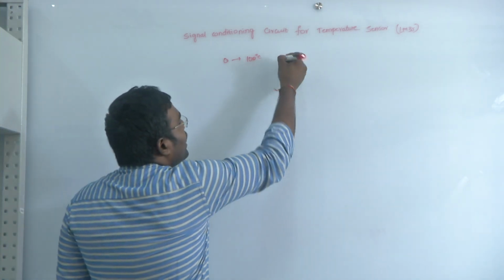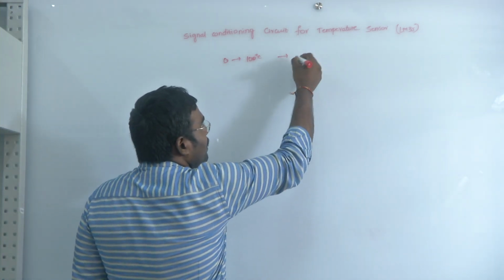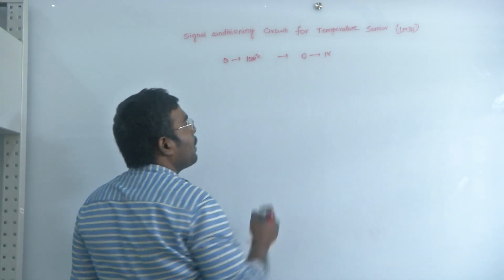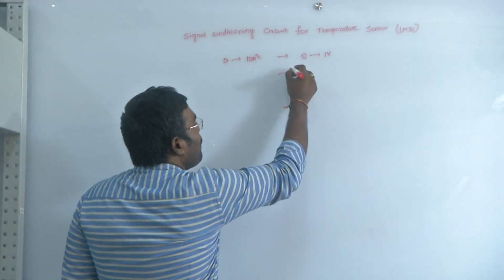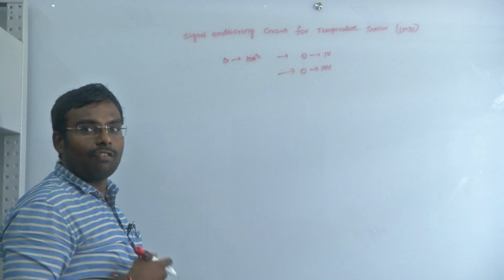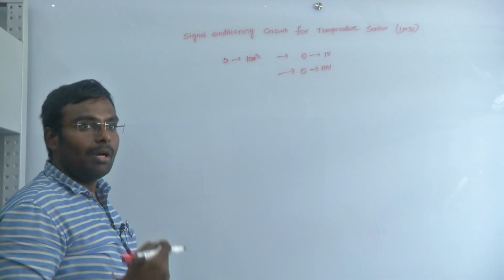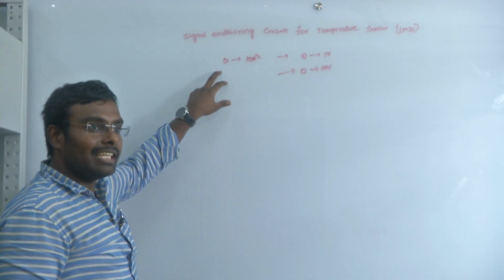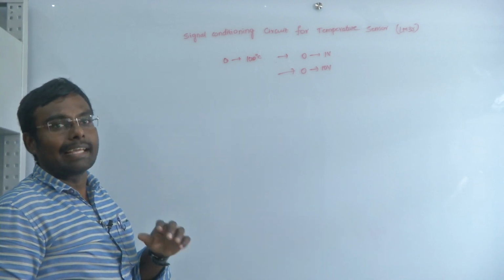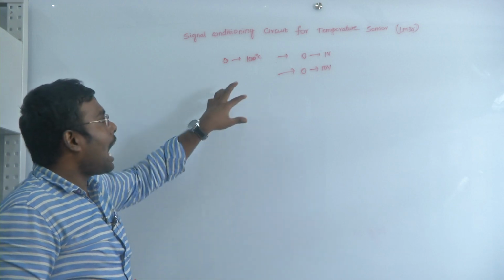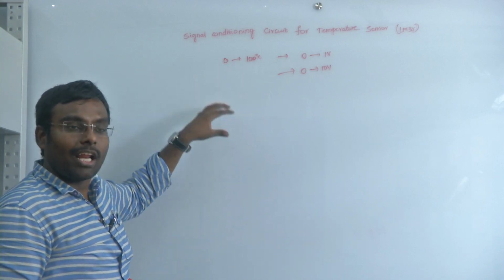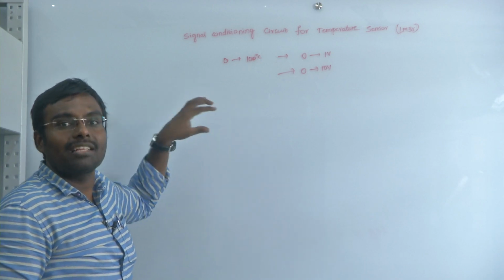Generally we get an output of 0 millivolt to 1 volt, but if we can implement 0 to 10 volts, then the resolution of the system will be higher. The minimum change that it can record is 0.39 degrees centigrade, provided our temperature sensor changes or provides an output signal for a change of 0.39 degrees centigrade.